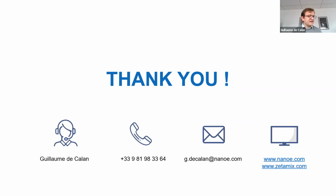What we usually say is, for a part that you know well and a material that you know well, good precision would be plus or minus 0.1 millimeter, with parts up to, let's say, 5, maybe 10 centimeters. This is really the best you can reach, plus or minus 0.1.